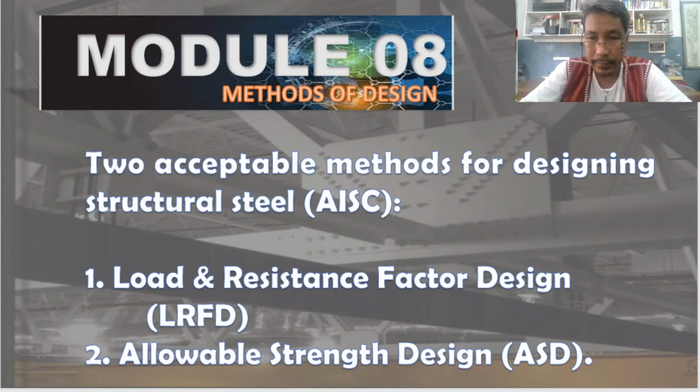Some authors say allowable stress design. This author is using the word allowable strength design. So actually, strength design is LRFD, and stress design or allowable stress design is ASD. This is usual.